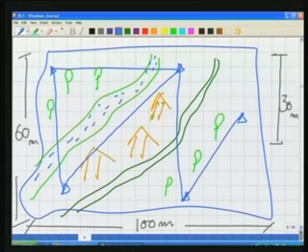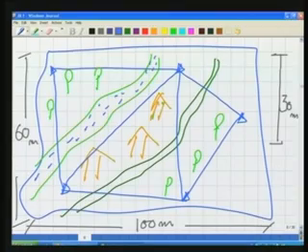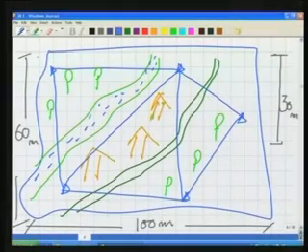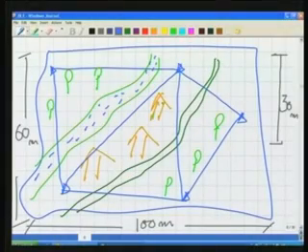Let us say that is your network. We will understand very soon the utility of this. You decide about this. This network is also decided at the stage of reconnaissance. You decide about those points which will become your control points. Now, why do we want to do it? We want to do it because by establishing some points and measuring the distance between these points very accurately, we can take this skeleton of the area into the laboratory.